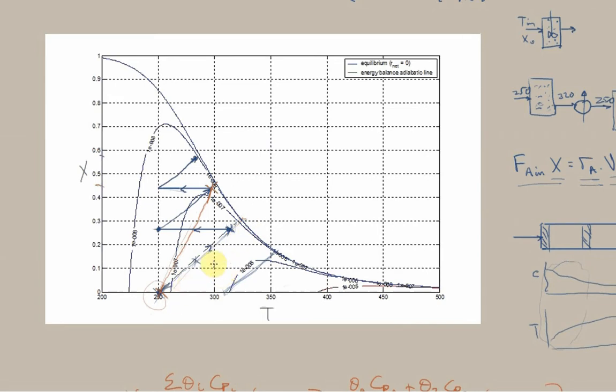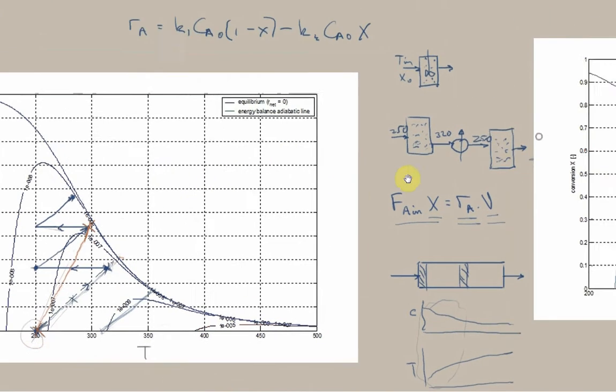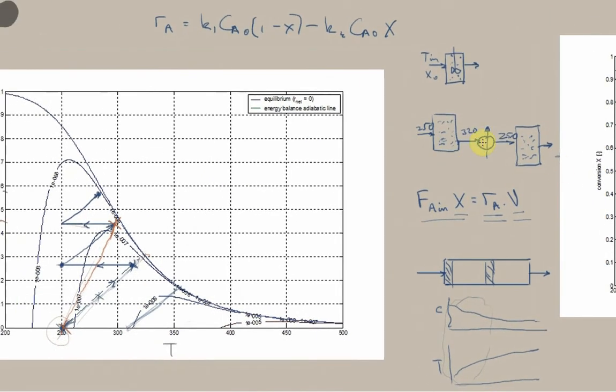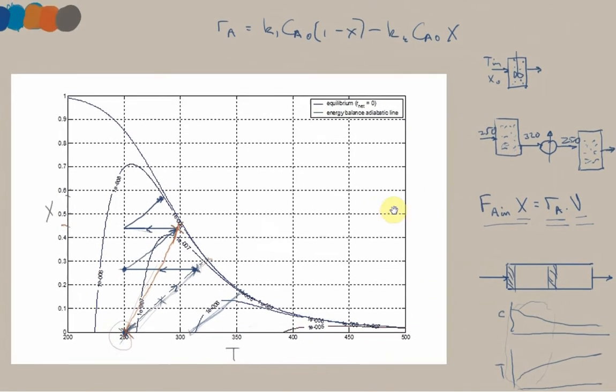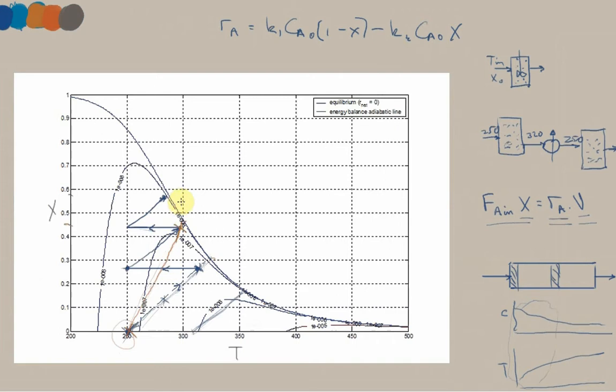And typically, we are trying to reduce the volume of our reactor system. If we can reduce the volume of our reactors, that normally means the expense is reduced. So we could try and reduce the capital expense of the system. It could also be the overall conversion. So let's say our reaction mixture consists of components which are difficult to separate. It would be much better to convert as much as we can to the product range. If we have a high concentration of product, then there's less separation to do.